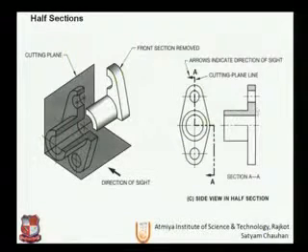So we have seen the cutting section in the upper half only, and for the bottom part we have seen this side. It means that this part is completely visible, and this is the cut section. So this is a half cut section, so it's called half section.